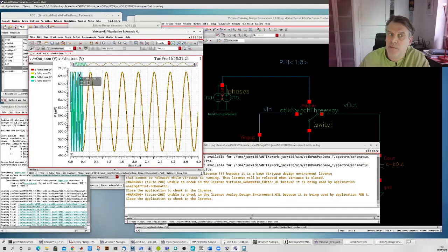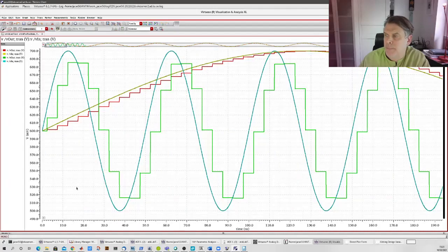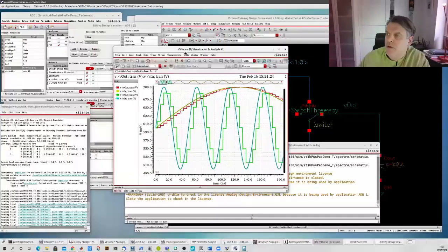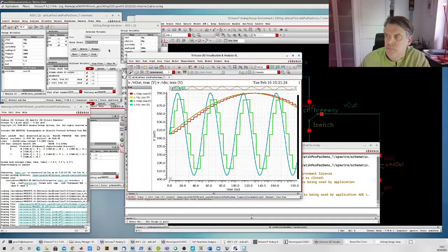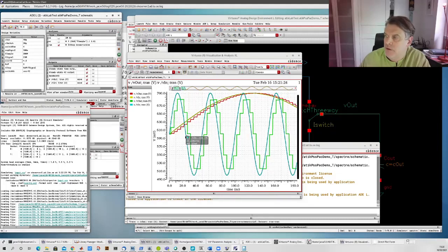Anyway, so I still simulate the same number of periods here in my simulation graph. 8 of them, it seems, and then I have 8 periods also at the lower frequency. So here we can see the blue one is the input signal, the green one is the sampled, and now we see there is a loss in amplitude, and there is also phase shift happening here. So I'm approaching the pole of my system. Okay, so one thing one could do now is to simply run the sampling and the transient analysis and maybe loop the signal frequency and measure where we lose X dBs or something, or a certain amplitude level. And then you can find the bandwidth of your system in that way. So it's obviously a bit tedious. Transient simulations are quite time consuming, and they're also power hungry, memory hungry, etc. Sorry, disk space hungry.